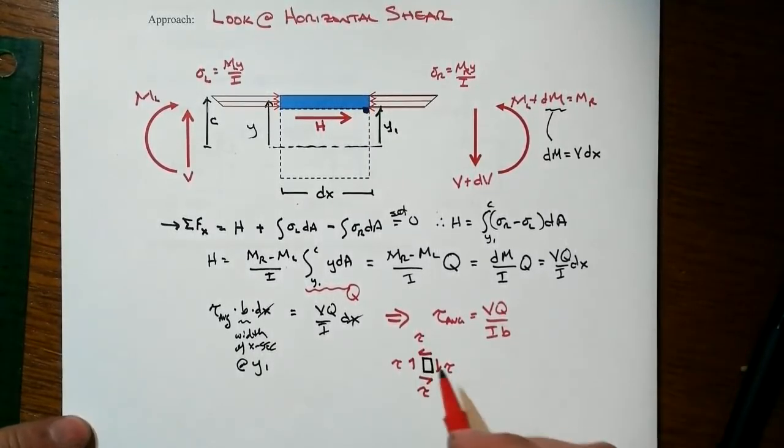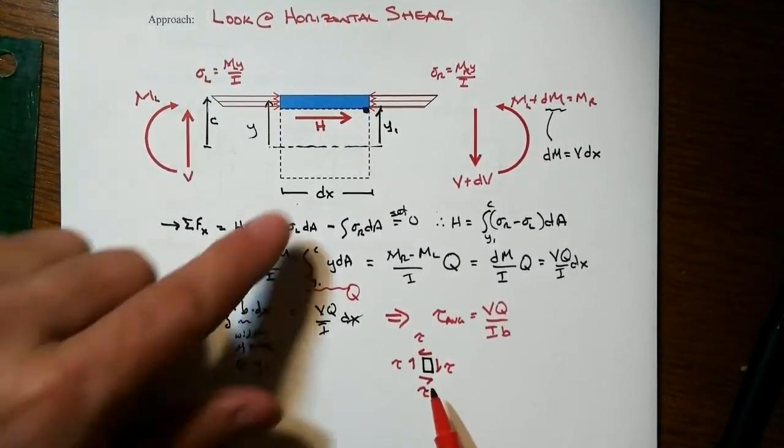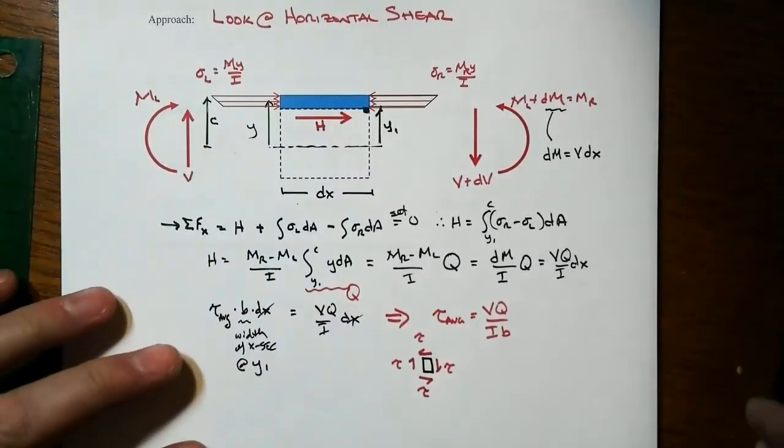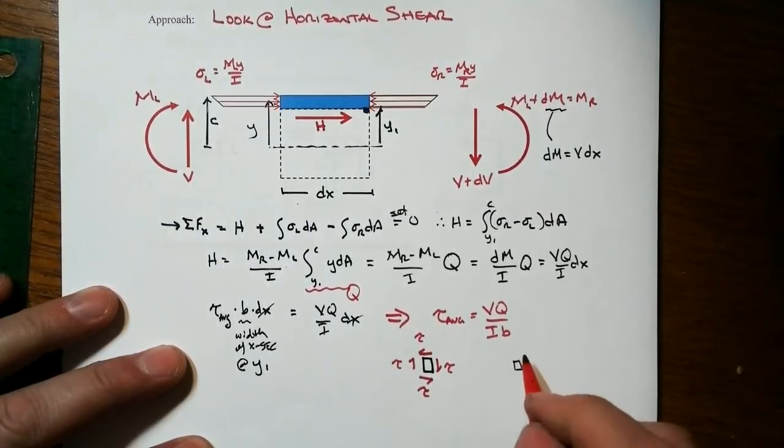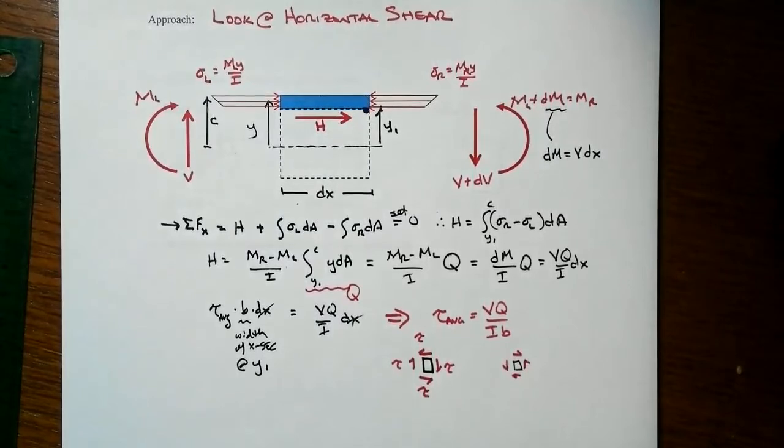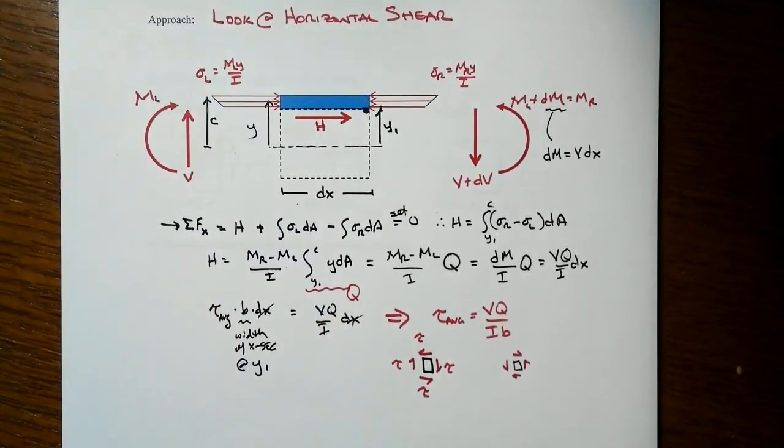And so we're either going to have that set up, which is exactly what we've got set up over here, or we have to have the other one, which would be in the other direction, right? Those shear stresses tend to pinch in different directions. So pulling, elongating this way on this one, pulling, elongating the other way, and shortening in the opposite direction, which is exactly why we see those 45-degree kinds of cracks in that reinforced concrete model that we saw.